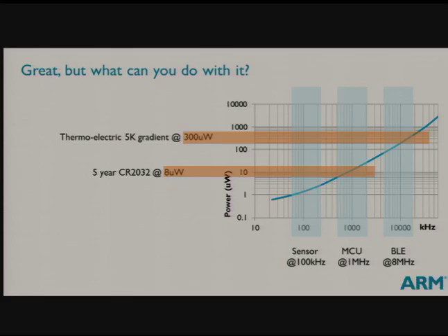You have to look at what your power source is. You have to look at what its real internal discharge is. What system can you really build? You might go, you know what, I'm just going to run my microprocessor flat out continuously. There's no point in worrying about all these duty cycles because what's the difference between 5 years and 9 years? So you really have to look at your system, and it's maybe not obvious what optimizations you should be taking when in order to build that lowest power system. It might be more efficient to run it all the time at a lower voltage than spend lots of effort to work out when you're power gating it, when you're running all of these different things. So some of it becomes counterintuitive.